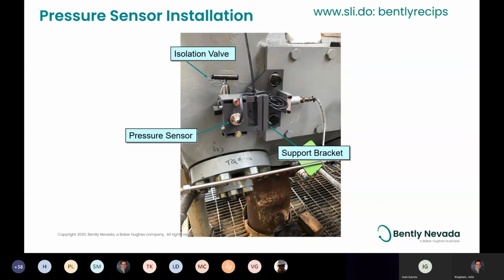Were there any considerations for the port length? Our projects guys do design the port lengths to make sure that, if it's too long, you'll get recompression of the gas because it never escapes, and it will build up in temperature. So we have to make sure that the temperature never exceeds the temperature capability of the sensor. That's one of the considerations.